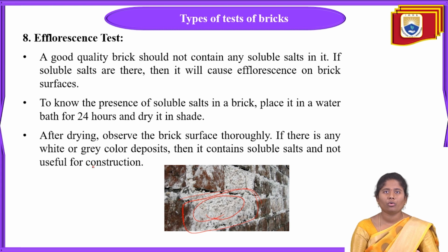Firstly, for this efflorescence test, to know the presence of these soluble salts, just take one brick and place that brick in a water bath for 24 hours. For 24 hours, we are going to keep this brick in the water bath, and then it can be dried in the sunshade.